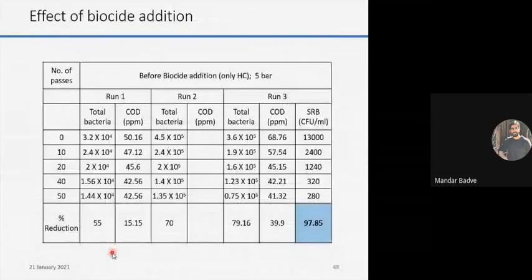Then we used the combination of biocide, because they had their own biocide which they were using for disinfection. Then we did the experiment with biocide and without biocide as well. So this was before biocide addition, only hydrodynamic cavitation. We observed that with only hydrodynamic cavitation, we achieved almost 98% reduction in sulfate reducing bacteria. These are the main bacteria which contribute majorly to biofouling, right? Therefore, we focused on these specific bacteria as well.